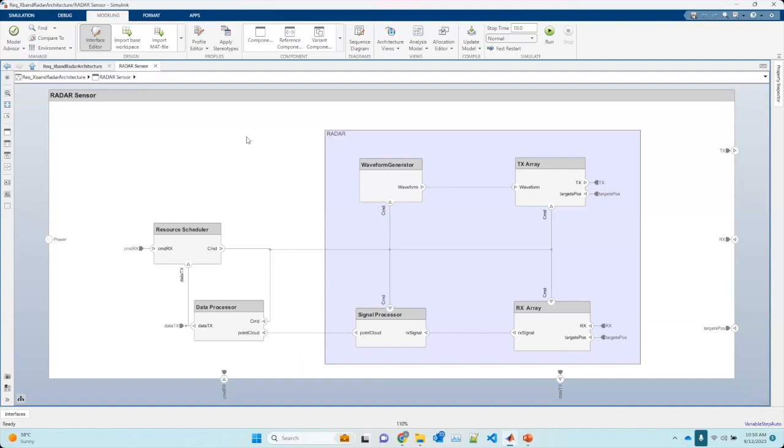So you can use System Composer to decompose further your components, and you can also do the connection between the components. We do it this way. This is a sort of exit, and then we have a door here. So we can see this as output, and this as an input. And to do that is straightforward. You just hover on the components you want to connect, then you do it this way, and it's going to take you to the other one. Let me just remove this one.